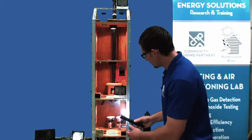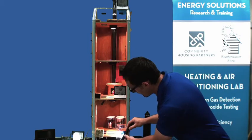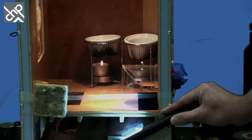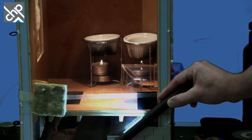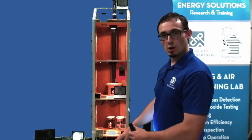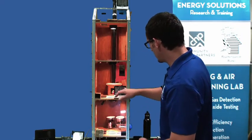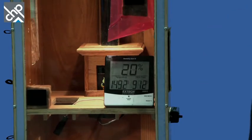My gauge hasn't quite caught up to what's going on here. I don't know if you guys can see that down at the bottom. Starting to see, what is that? Getting a little froggy in the basement there. So we're starting to see that condensation, and as we theorized, it's starting at the lowest point in the building and then it's going to start spreading, because again, that should be the lowest surface temperature that you've got in the building. We're going to keep an eye on this as it develops here. 21% now. Dew point 92.8. We're getting in the zone. This is going to be really close.